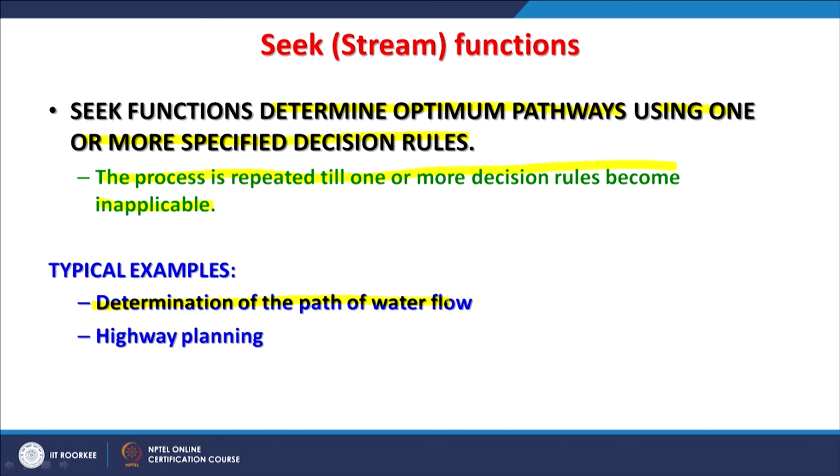So, using a digital elevation model, one can determine even a drainage network, and sometimes a very accurate drainage network or stream network you can do. Once the stream network is there, then a person who works in hydrology will ask, can you develop a stream ordering, which are the first order stream, second order, third order, based on two very popular schemes. One is Strahler and Shreve, and you say yes, I can do it.